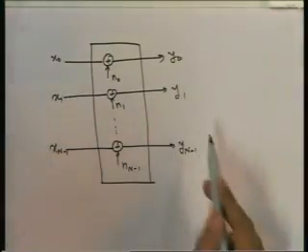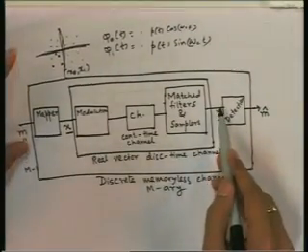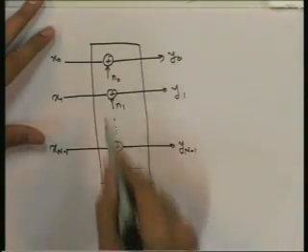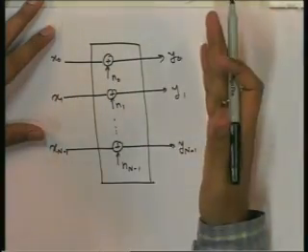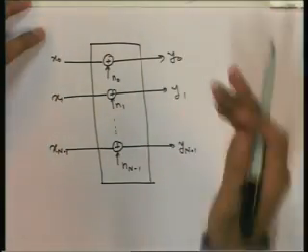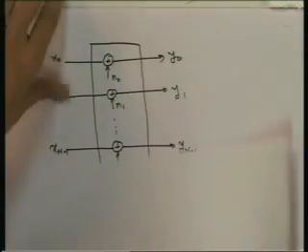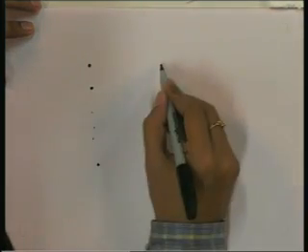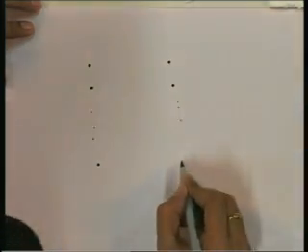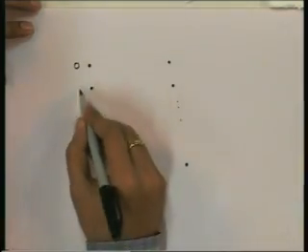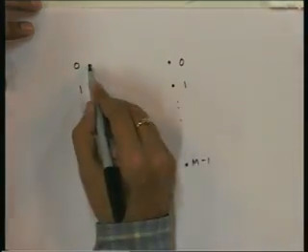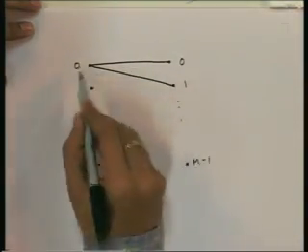So, x vector and y vector, and we have also discussed before that component wise y1 is x1 plus n1 and so on. Noise is being added. So, there is a noise vector which is being added to the transmitted vector, and the received vector is the result of that. Then we have also discussed the M-ary discrete memoryless channel model, where there are M possible transmitted values and M possible received values, 0, 1, M minus 1, 0, 1, M minus 1, and there is some transition probability.